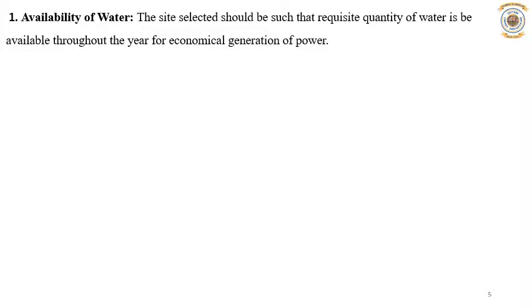Again, while selecting a dam, you should consider the nature of the foundation, the nature of the valley, and the type of dam. Then whether it is a sound rock formation in the foundation or poor rock in an earth foundation. Then you should study the permeability of the foundation material. So these are the important points.